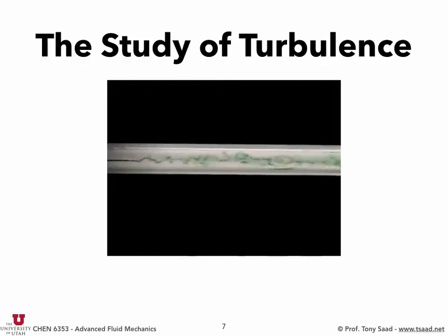We're turbulent. Velocity is fluctuating in time and in space. It's changing. Okay? You're fully turbulent. However, the flow is still, on average, the same, right? It's still moving in that direction. You need to have your average velocity because of mass conservation. Your average velocity at any cross-section of the pipe needs to be equal to the average velocity at the inlet. So we retain those properties, right? Those average properties, and that's going to be a key element in our tackling the turbulence problem.